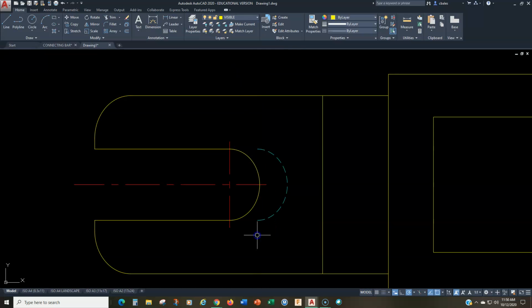We can get rid of that. And then we're going to draw a hidden line. So let's change the layer to hidden. We're going to draw a hidden line from here to here and to here and from here to here. There we go. All right. So, and again, no center mark back there. Don't worry about the center mark not meeting. Fine. You know, we can't control all that. That's fine.